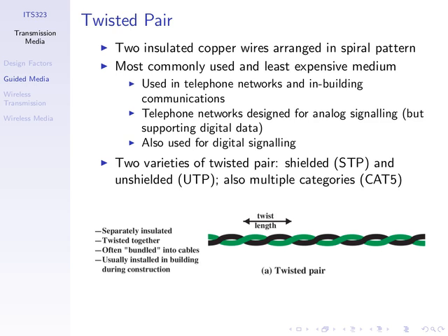So shielding can give us better quality signals, but in practice it becomes hard to deploy. To put cables along the floor and up through the ceilings and install them, if they do not bend very well, they're very hard to install. So the most common form of twisted pair is unshielded twisted pair. That's what these are.